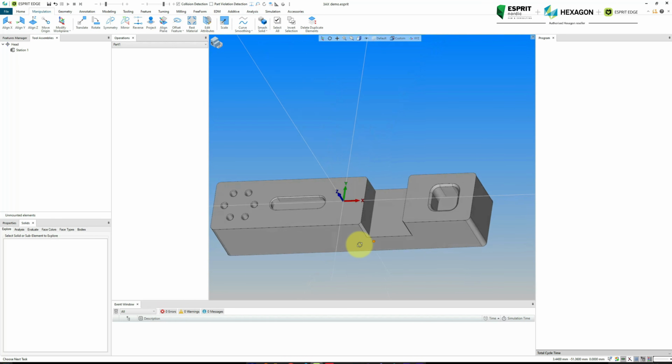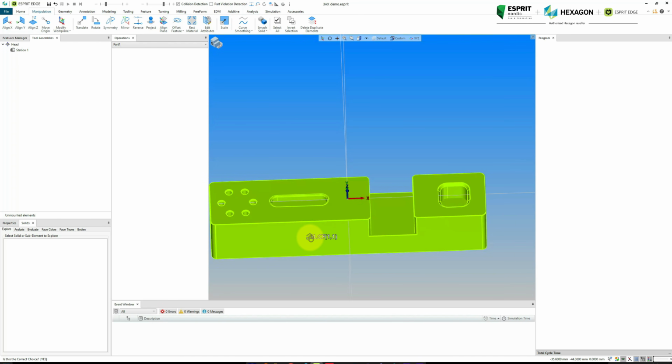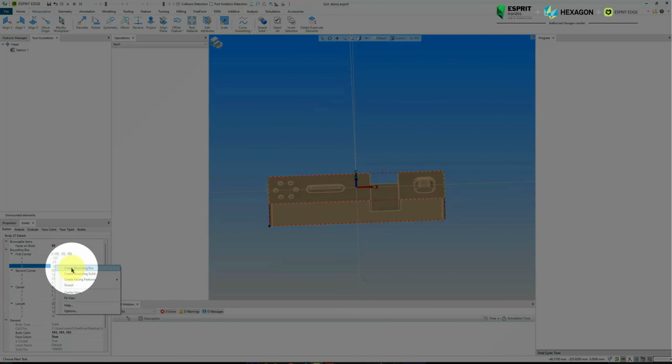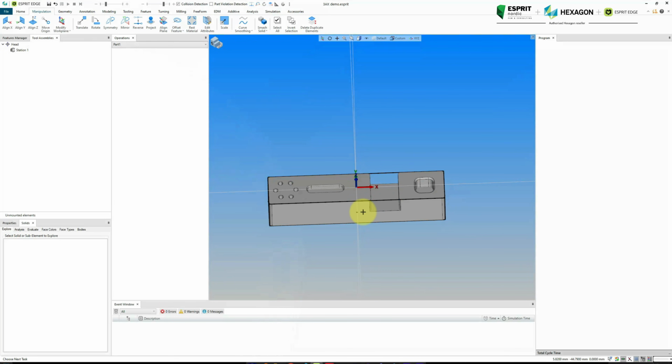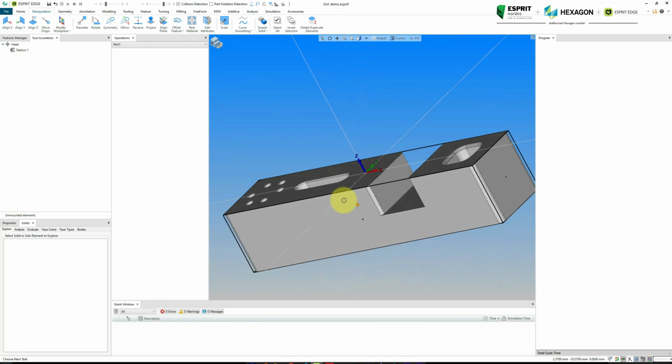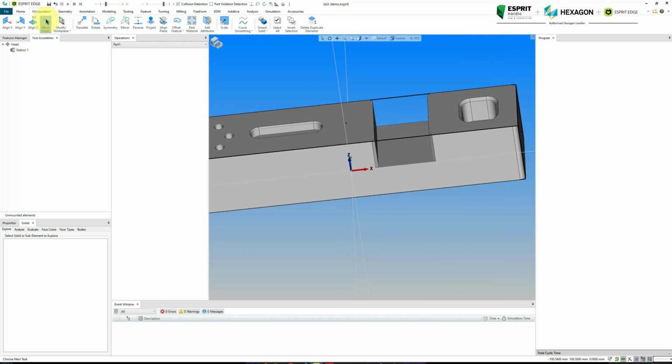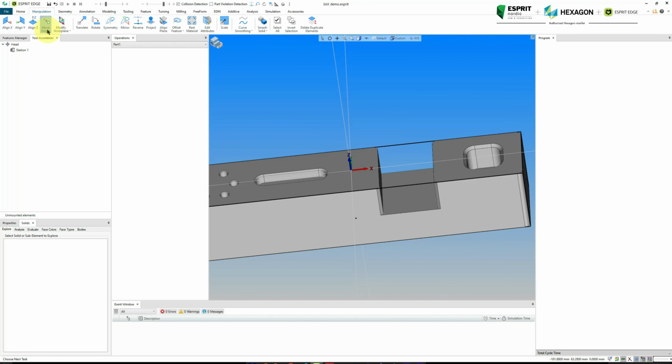After aligning the Z-axis, I'll select the entire model. This allows me to create a bounding box around it. With the bounding box established, I can use the Move Origin function within the Manipulation tab. This powerful tool lets me precisely snap the part to various endpoints or midpoints of the model for accurate positioning.